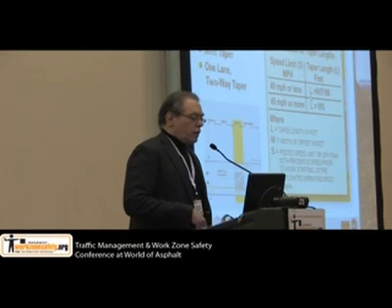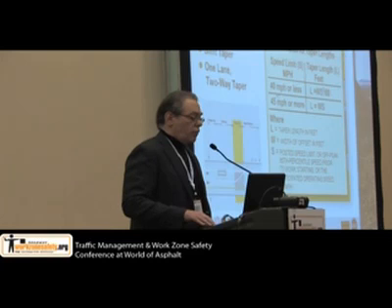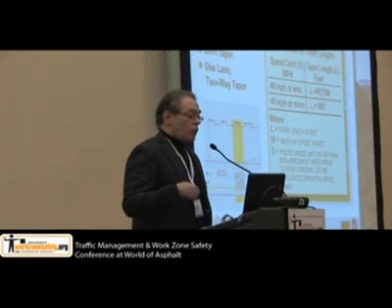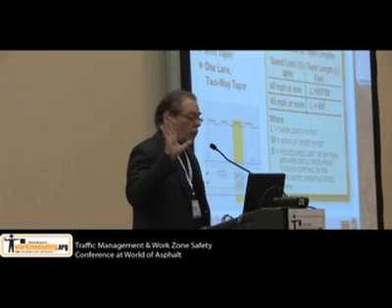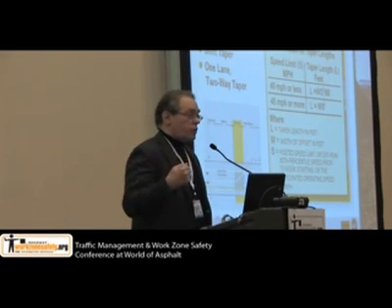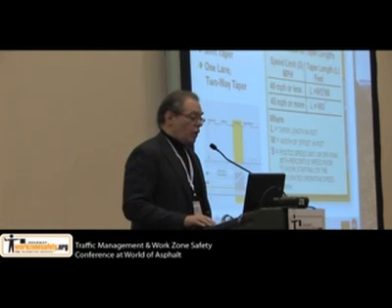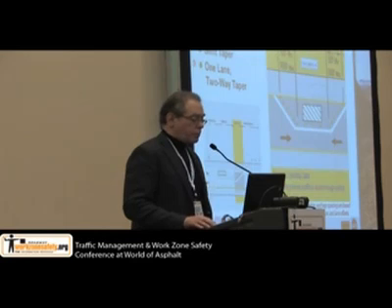Table 6C4, of course, actually gives us our formulas if we want to calculate them for the speed in miles per hour, where we have the L, the taper length, based upon the width of the offset. So we're actually using offset times the speed. So when we're trying to figure out the taper length, what are we using? We're using the width of the offset plus the speed, and that formula ultimately gives us the value of L, which is the final method for determining the taper.